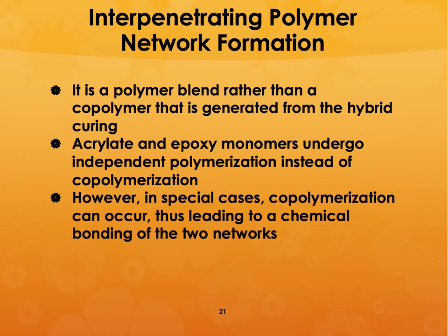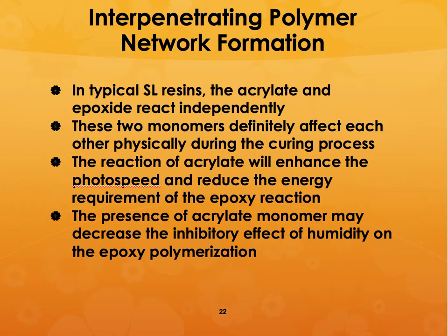There could be some cases where copolymerization occurs, in which case you have a chemical bonding of the two networks. But most of the time it doesn't happen. They react independently and they definitely affect each other physically during the curing process. The acrylate will react very quickly, but the epoxide would reduce the amount of shrinkage.